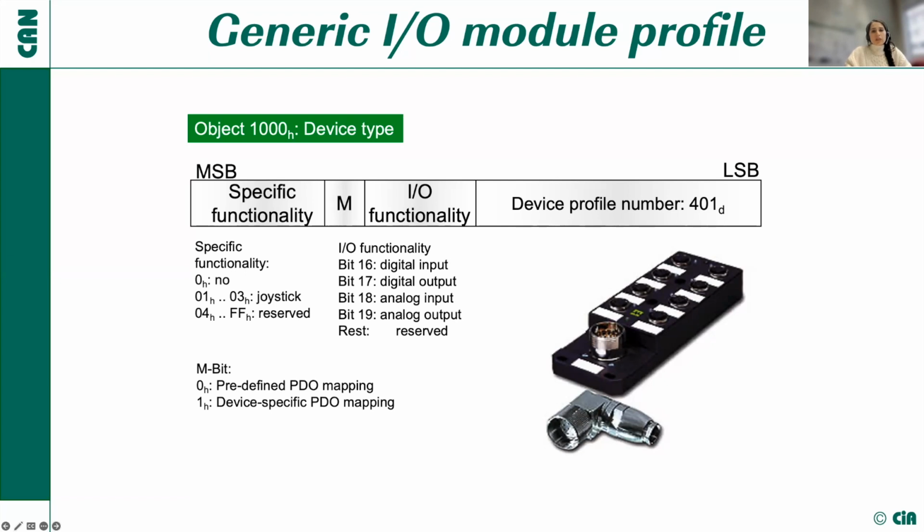Here is the most used profile, 401 for generic I/O modules, which describes CANopen interfaces for modular devices with analog and digital inputs and outputs. As a designer, you don't have to implement all of the I/O profile functionality in your microcontroller.